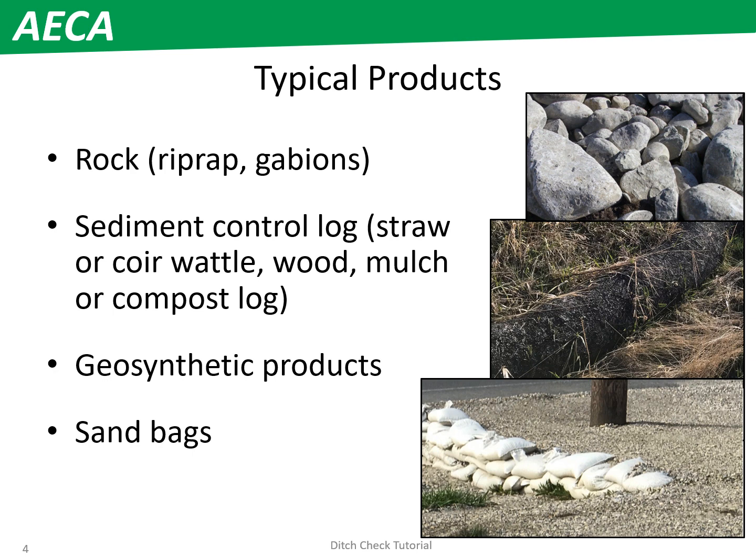Sandbags could be used for a temporary installation to mitigate against erosion in a ditch prior to the ditch reaching final grade, and prior to the application of topsoil and seed.